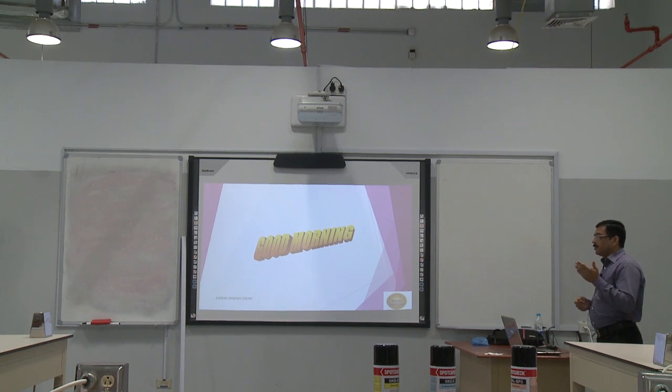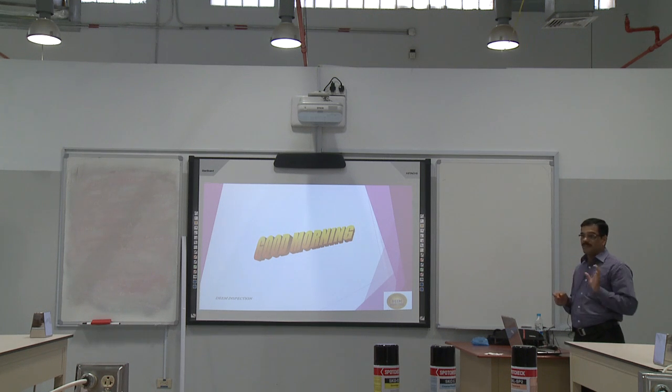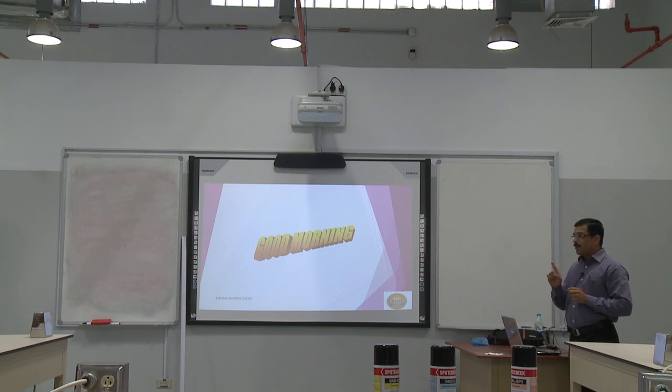So, in the NDT method, magnetic particle testing, yesterday we were talking about magnetic particle testing, which is done on ferromagnetic material to detect surface and near surface discontinuities. One of the major limitations we observed is that magnetic particle testing can be used only on ferromagnetic material. Other material is not possible because we cannot magnetize it.